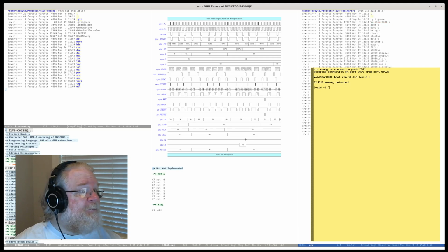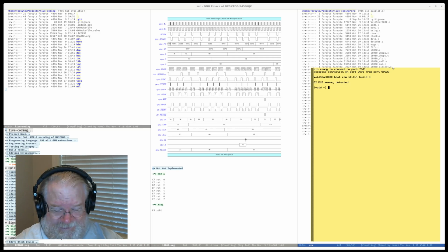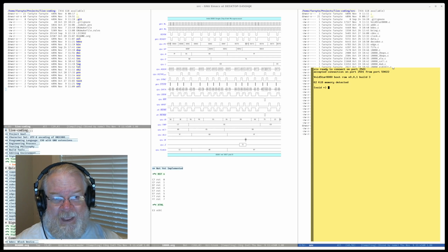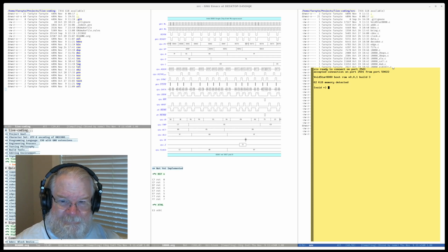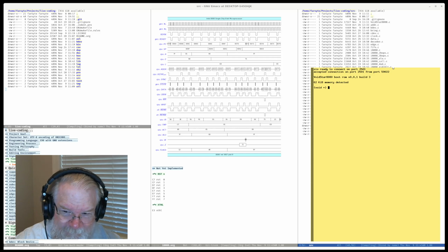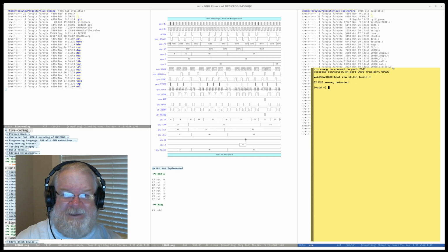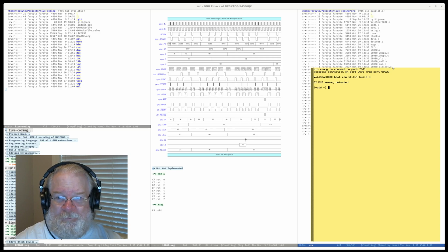Got to get rid of editor temporary. Keep it clean. So did that and got it assembled. So got from an assembly file to a listing file and a hex file, and realized FigForth doesn't run in ROMs. You can make it ROMable, but if you are starting with an assembly code file, the changes to make FigForth ROMable are kind of nitpicky to get done. So I thought, well,